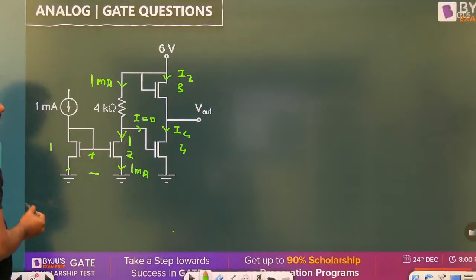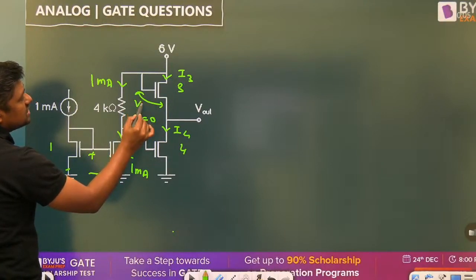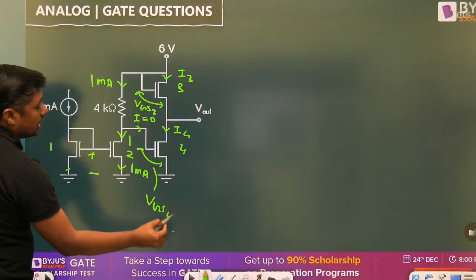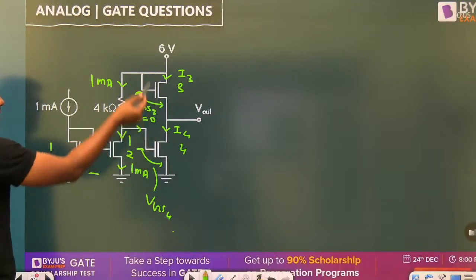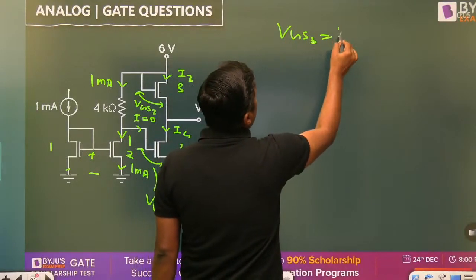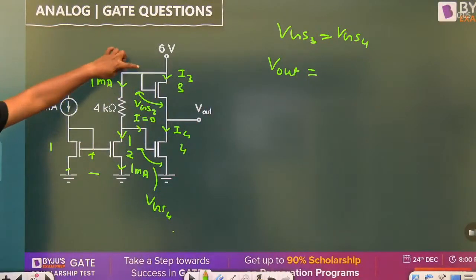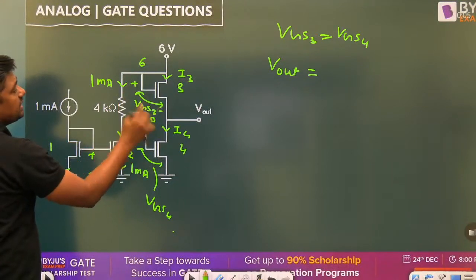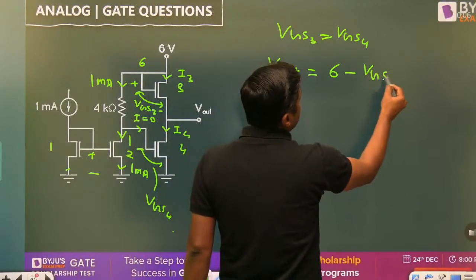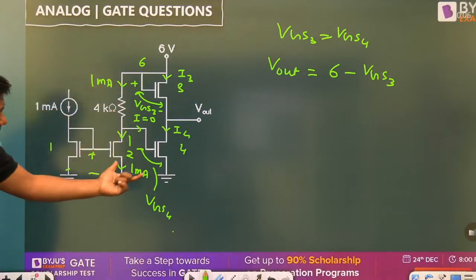Because in the gate terminal, what is the current? 0. Now, we want Vout. Then what is the voltage at this point? Let this be VGS3, and this VGS4. Now, the current is the same, the characteristics are the same, everything is the same. Therefore, VGS4 and VGS3 are equal. Why are we calculating VGS3? Because the voltage at this point is 6 volt. When we subtract VGS3 from 6 volt, you will get Vout. Vout is nothing but 6 minus VGS3. Now tell me, what is VGS4?